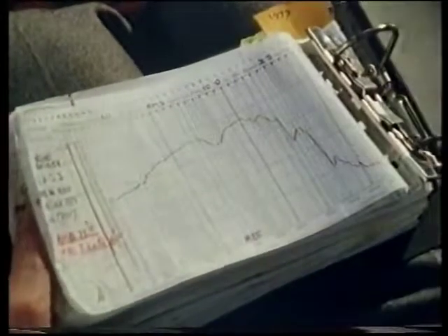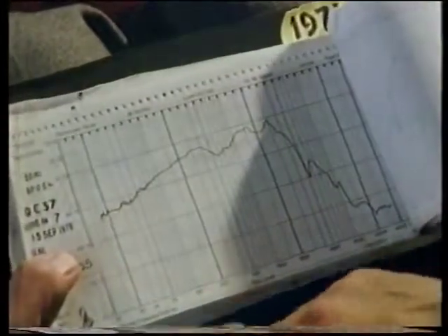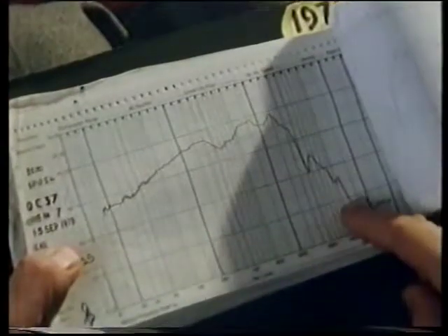The acoustical characteristics of loudspeakers have traditionally been measured in terms of frequency using a variable frequency generator of sinusoidal waveforms as a signal source. Curves such as this, which are fairly typical of this kind of measurement, in fact show the transfer function of a particular drive unit, plotting sound level against log frequency. The equipment for doing this kind of work is relatively inexpensive, but it does need a very special environment in order to give highly accurate results.